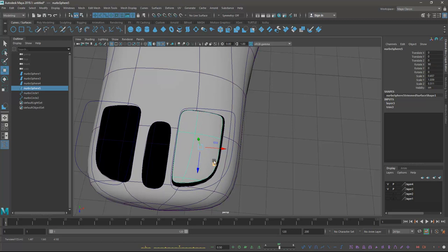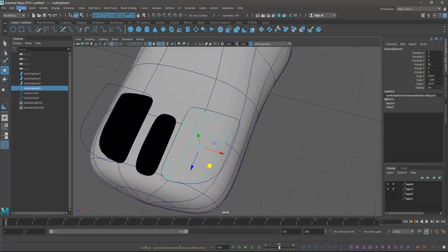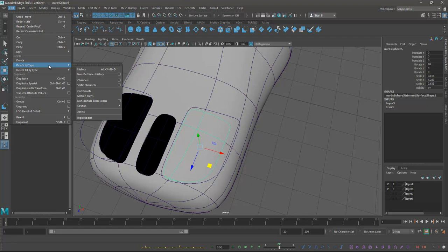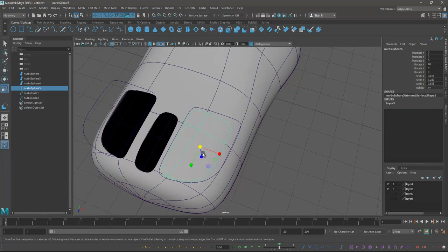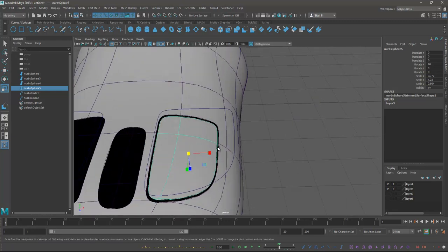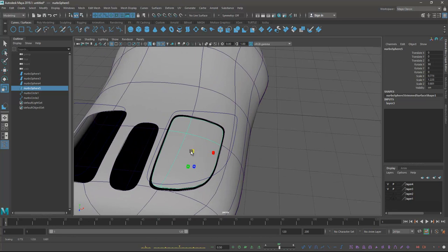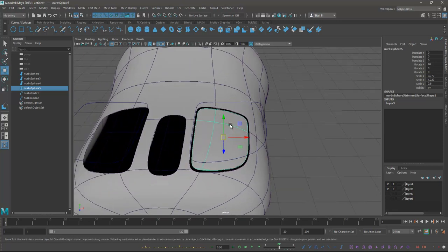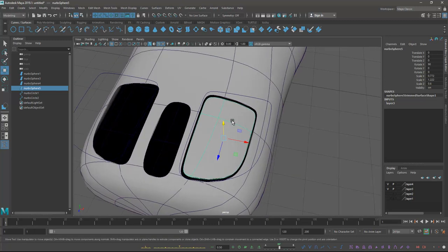So this time I'm scaling this button a little smaller. Before scaling I'm going to delete history of the particular object. Now you can scale it. Why? Because if history is there, even if you scale, it does not scale properly. See, this way you can make a button like this, and you can also bring it up, or bring it down, let it be equal, that would be cool.